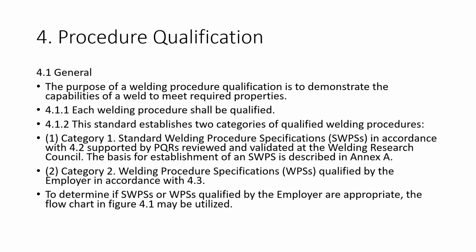So if you need a welding procedure on a specific type of material and you don't want to qualify it, you can call up AWS, the American Welding Society, or look on their website, and they've got a whole laundry list of these SWPSs, Standard Welding Procedure Specifications. So then you don't have to go through and qualify a weld procedure. You can just use one of theirs, weld the material, you're good to go. A lot of the American Welding Society codes allow you to do this. ASME Section 9 allows you to do this under some limitations.